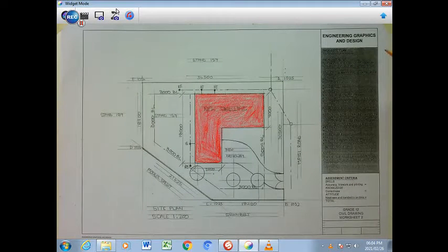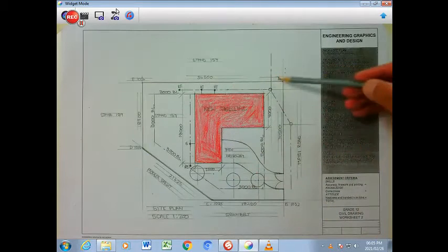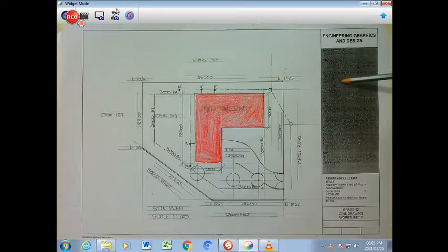Learners, so we check whether we comply with all the necessary detail and specifications which we had to implement on our site plan. So we're starting with the scale right there, and you can see that the scale is actually 1:200. We go on to the boundary lines. So the boundary lines are there. It's visible, nice and dark.